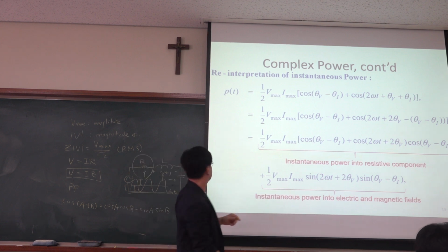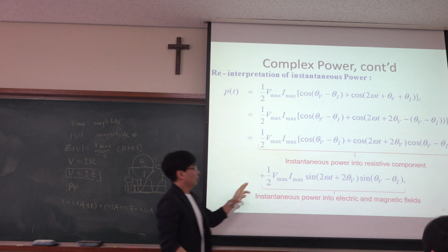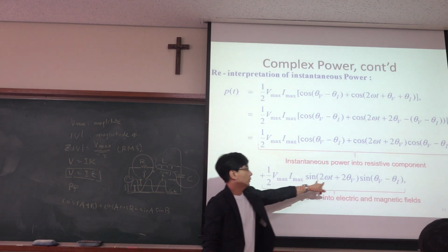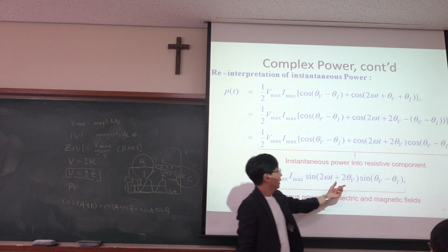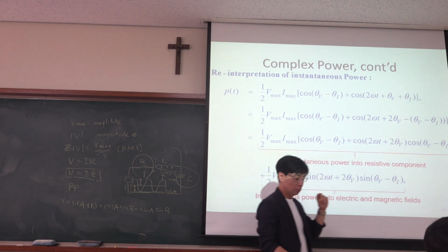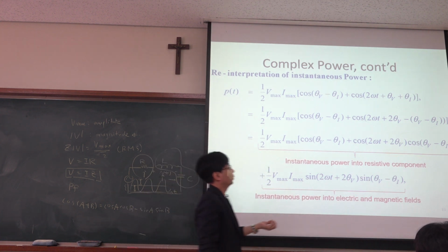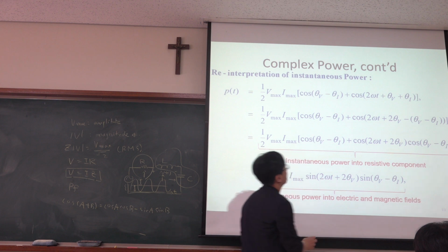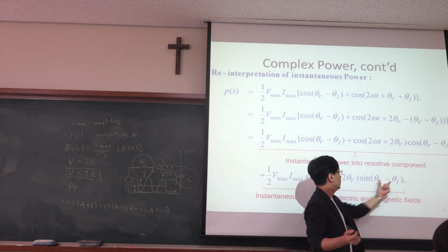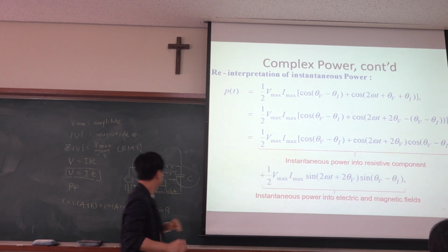And by contrast, the L and C consume instantaneous power at a frequency of 2 times f, and the amplitude is this much. So the amplitude is sine of the power factor angle. So when the power factor angle is 0, we do not have this term at all.